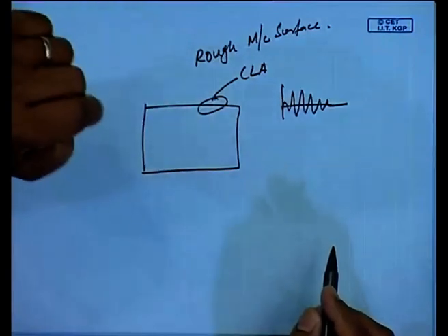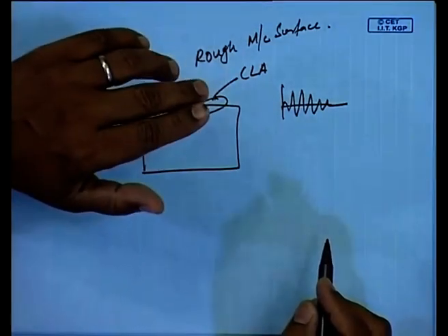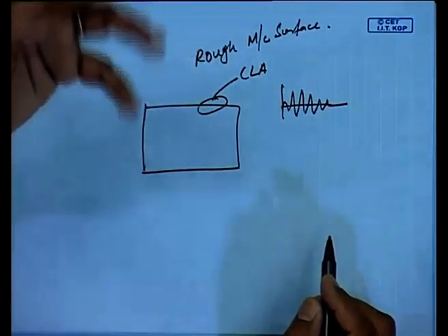Okay. There have been intermittent speed fluctuations in my machine, so these marks are going to stay in your machining process. So even a simple lathe machine has to be taken care of, otherwise if you are doing a machining operation on that lathe, the machine's quality is going to reflect on the workpiece. Okay. We take it for granted that you have a nice machine,